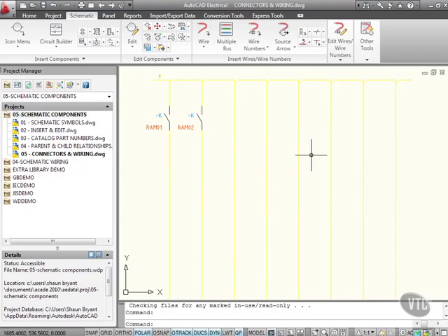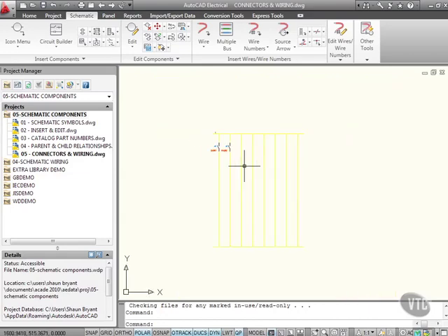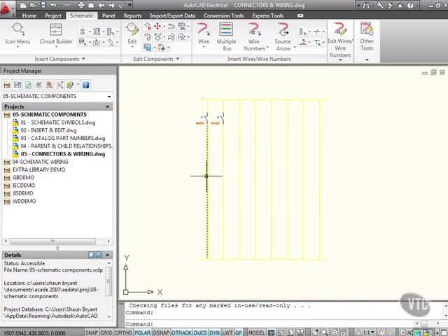Now I'm going to add a connector to this particular circuit here. I'll just zoom out slightly and you can see it there like so. Now the plan is to add a connector going horizontally across those 8 rungs there. Those 8 rungs I've already prepared for you, and they've got a spacing of 40 units, 40 millimeters, let's say.